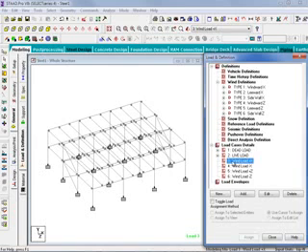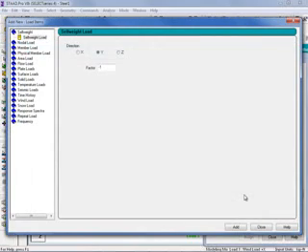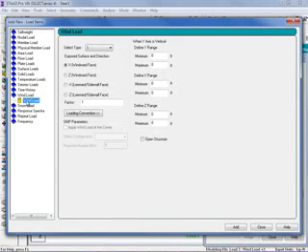So we will begin by selecting the appropriate load case and then clicking Add. In the Add New Load Items dialog, we will now select the wind load type. This load type would not have been available to us if we had not already entered a wind load definition for this model. The Select Type field instructs STAAD.Pro which wind definition would be appropriate for wind in this direction. So we'll select Type 1. This was our windward force in our X global axis direction.